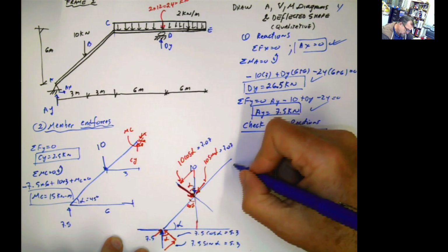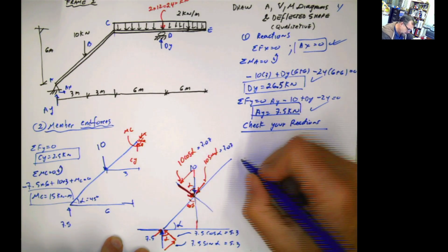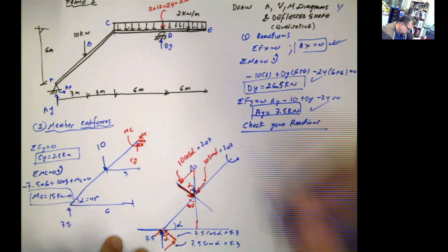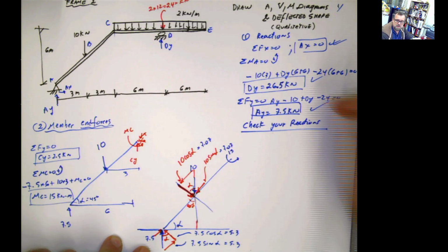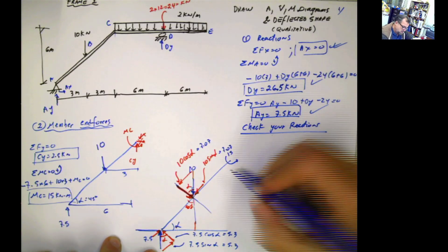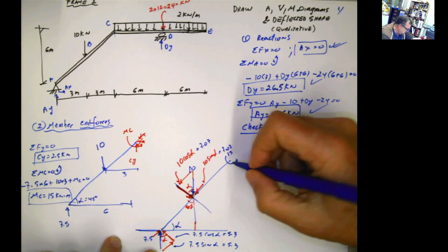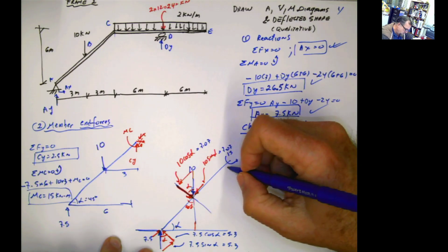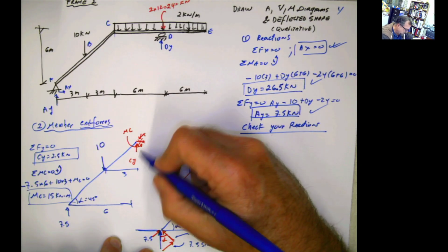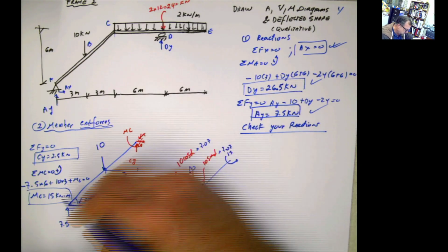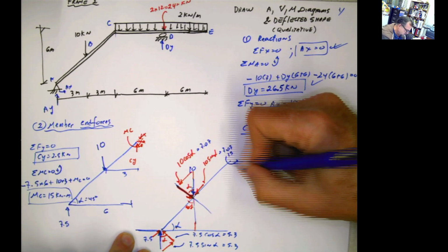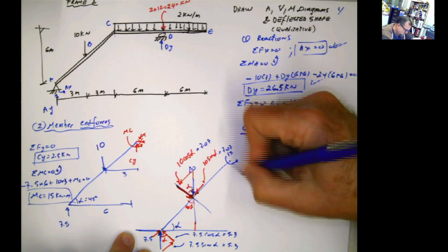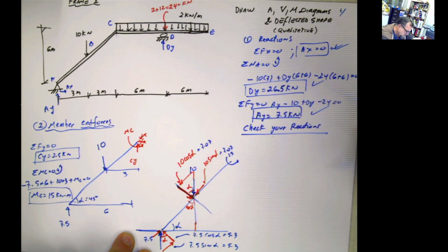Now, remember I had this force here. You can put it, the moment doesn't change, thank God for that. The moment is the moment. I'm not going to change that moment, it's 15. You don't have to rotate the moment because that's exactly what the moment is, rotation. But instead of me rotating this force of 2.5 that I put here, what I can do is summation of forces in this direction. That's what I can do, if I want to. Otherwise I can rotate that.